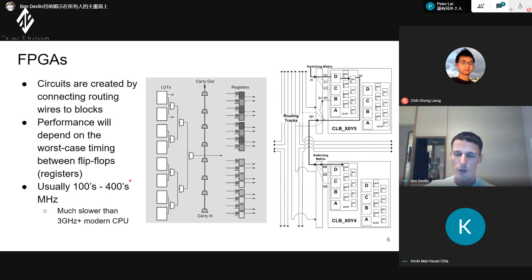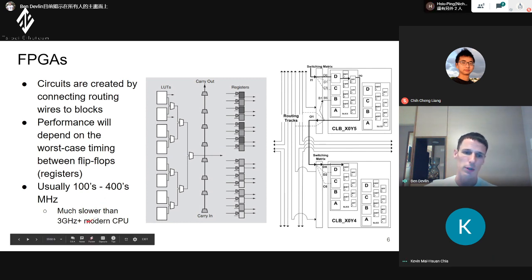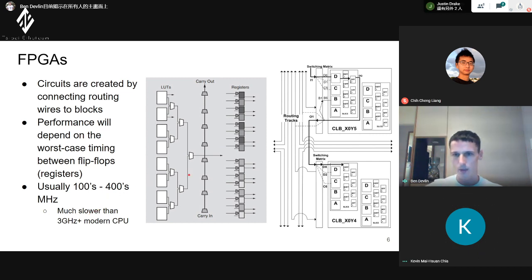So you can pretty much say that if the ASIC is going to be the same design, I can guarantee there's no parallelism that you can implement on the ASIC that the FPGA can't. The ASIC's advantage is only going to be that it doesn't have the switching. So you might get a clock speed coming up to 3 gigahertz, which is 10x. But it's never going to be 30 gigahertz. Thank you. Yeah, so this way you can show this.